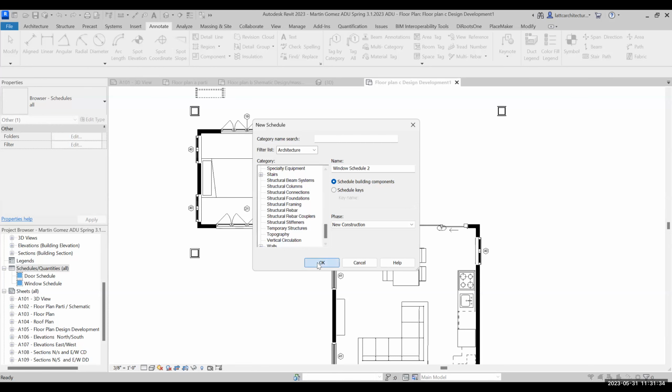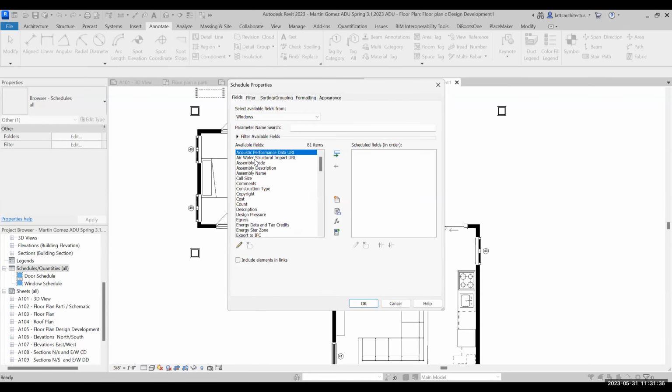and once you're in your schedule properties, you click by the category that you want to be mentioned on your schedules. So I chose the type. I went down and chose the count of them. Then we'll get to align them in order. I went to the height.